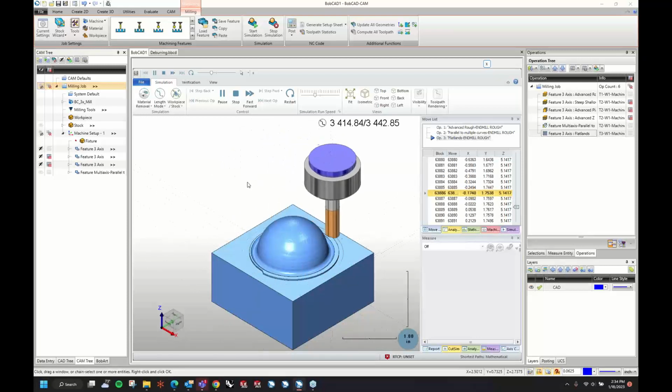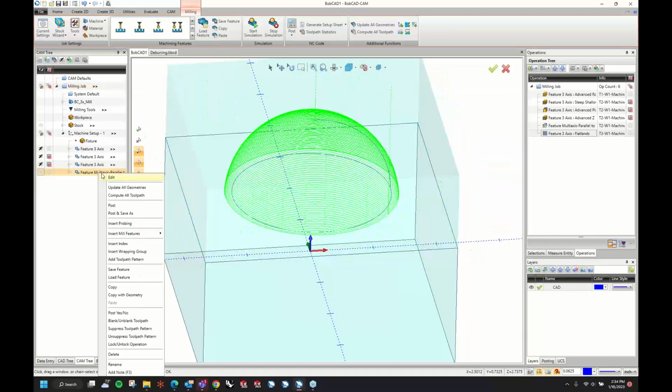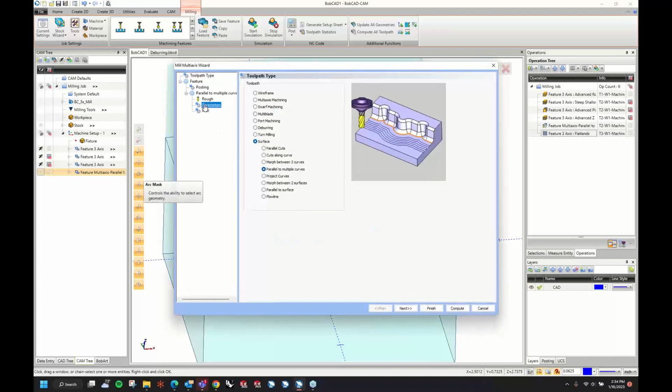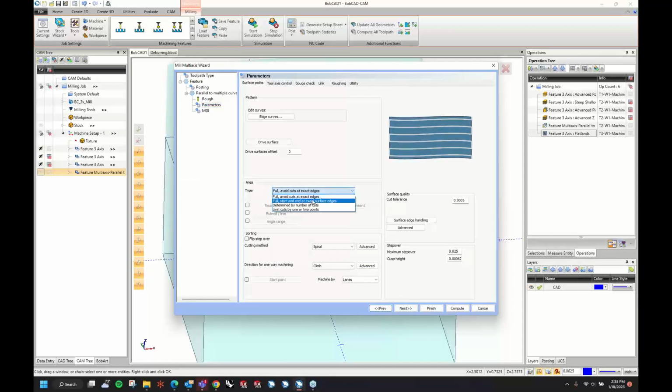So hopefully that lines up where they evenly connect, but if not, it's just playing around with those tolerances. I'd probably need to add a pencil still, or just have it go further and do a gouge check and see how that does. If I come back into this feature, let's say it didn't do the floor as much as I wanted, let's keep it on this.